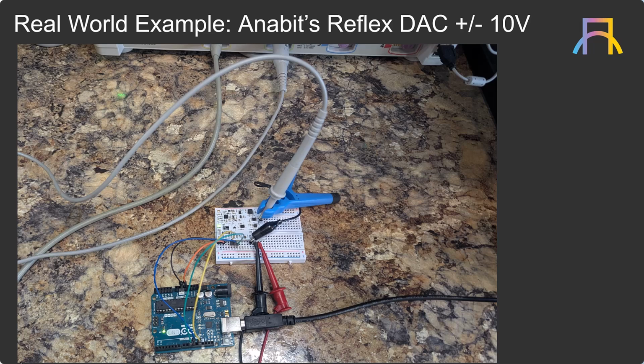And then I'm just using a simple Arduino Uno using SPI communication and a 5 volt input to power the board and control it. What I'm doing is I'm just generating a square wave signal that goes from the lowest value of the DAC to the highest value of the DAC. So to cover the whole range of the DAC and the output of the summing amplifier.